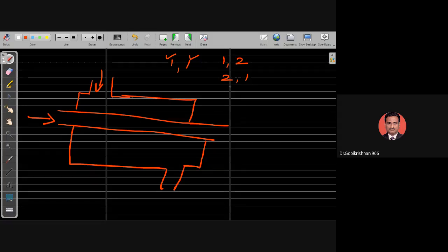The amount of latent heat will normally be higher than the amount of sensible heat or specific heat. That's why the hot fluid will most of the time be used in the form of a vapor. If you take methanol and water, methanol can be easily vaporized. Therefore, it can be taken as the hot fluid.